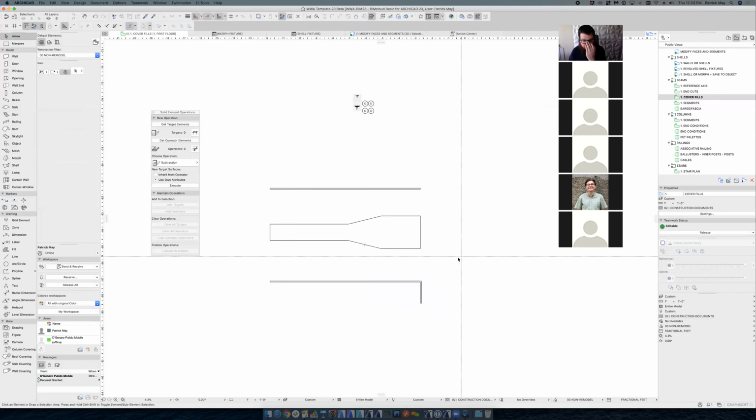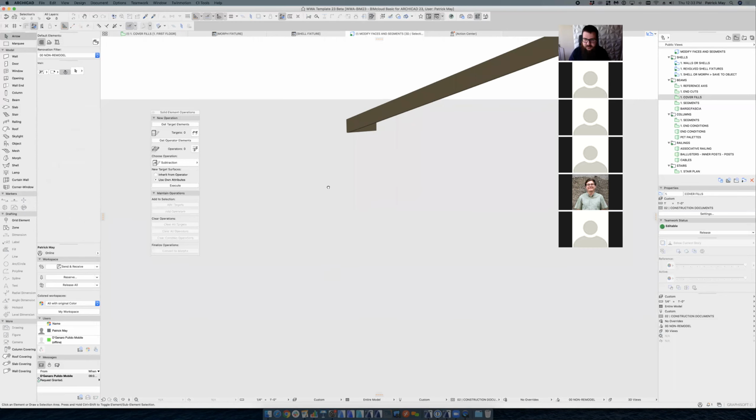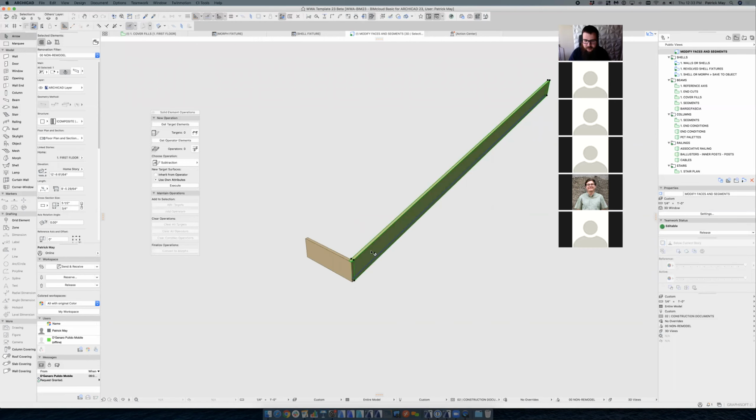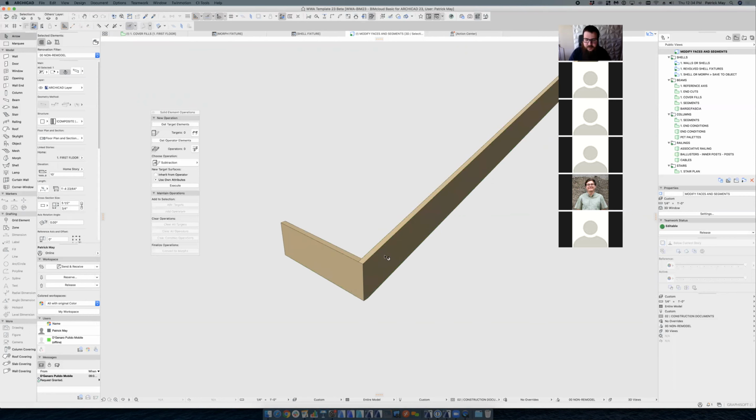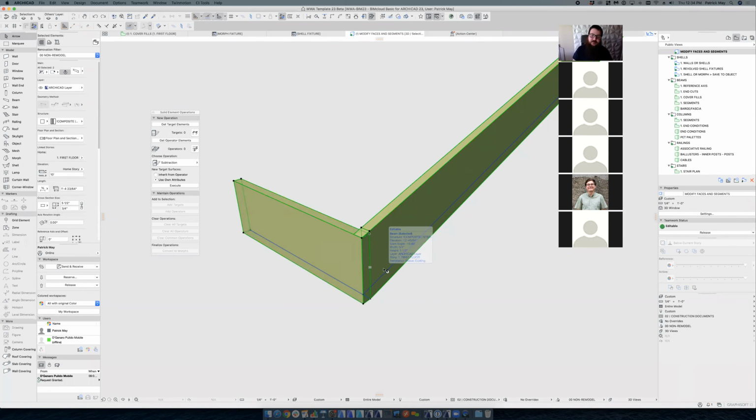The next thing about the beam tool that I honestly just noticed about 3 weeks ago is one that we run into pretty regularly, right, where we have a barge rafter and we have a fascia. The barge rafter is sloping, the fascia is not. Typically, when these intersect, we get this nasty junction. But because the reference line is customizable now, we can basically say that these two things intersect, but they don't intersect at that point. The intersection node isn't consistent. So that allows us to have basically a vertical eave fascia and a sloping barge board that clean up without having to have separate non-intersecting layers, which was our solution in the past.